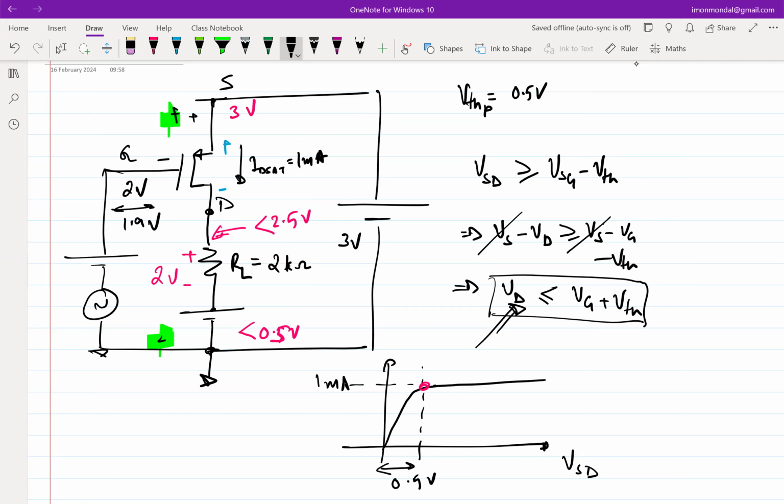So in this case, we start off with the assumption that the transistor is in saturation and then evaluate, with the conditions that are given, whether the transistor is in fact in saturation or not. If it's not, we'll go back and change the condition. I don't need to solve other equations to find out, if it's not in saturation, what the drain voltage, gate voltage, and so on will be. So under this condition, can you tell me, if this goes to 1.9, what is likely to change, assuming the transistor is in saturation?